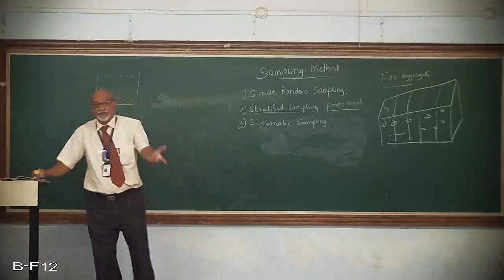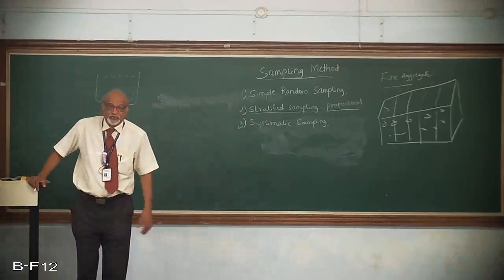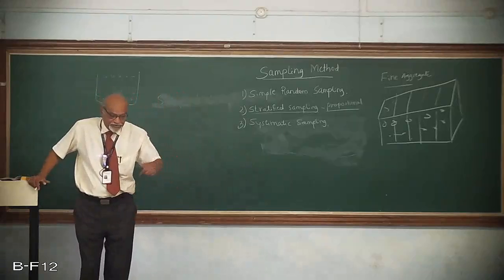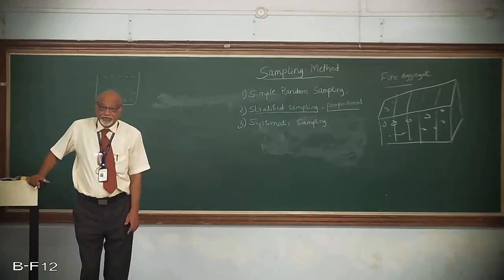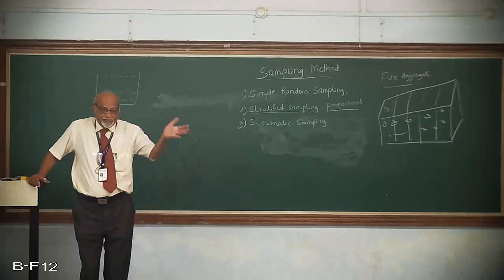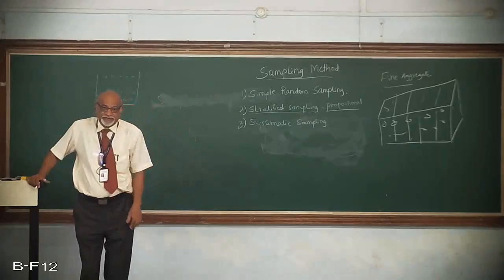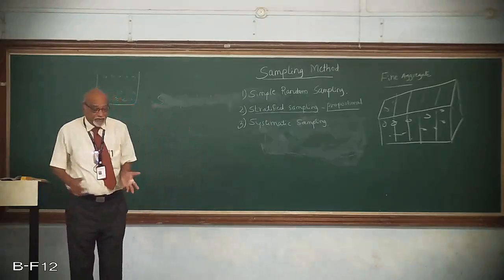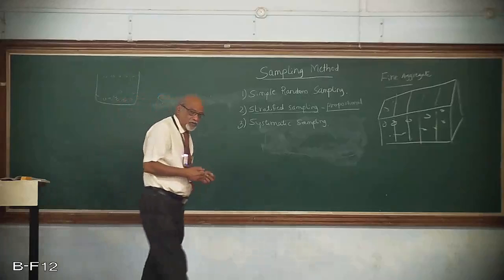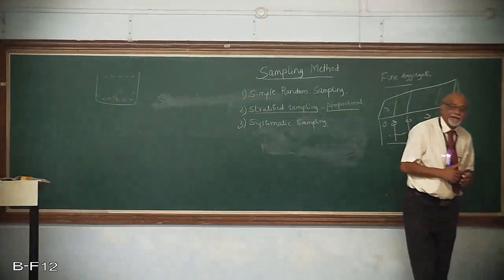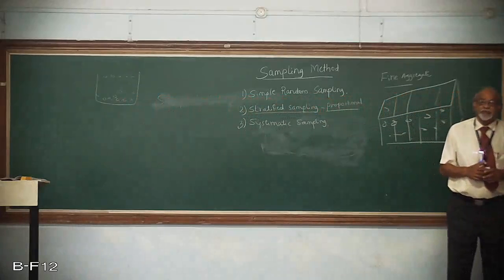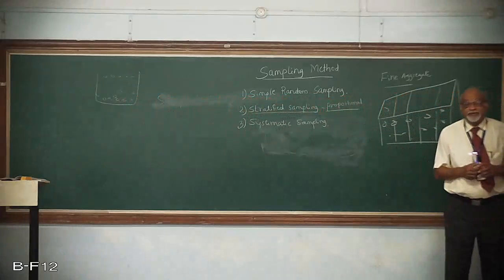Okay, we want to inspect. For example, that is what I told you, cement bags. I want to test it, because you might know the test of the cement is to be carried out. But you would have supplied some 1,000 bags of cement. If I want to test all, if I open up all these cement bags, then I cannot store them properly. Then how is it to be done?